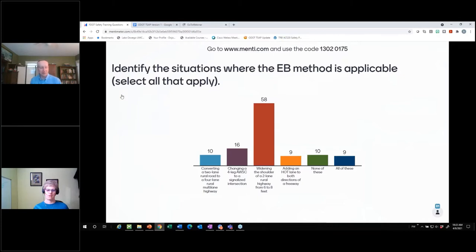And I guess it's pretty important for us to be clear and point out, unless you're using it for PSI and historical analysis, you absolutely should not use it for 1, 2, or 4 for a future comparison to modify predictive, because the crashes on the road for the last 5 years are not going to be a good indication of future crashes once you've made these fairly substantial improvements.